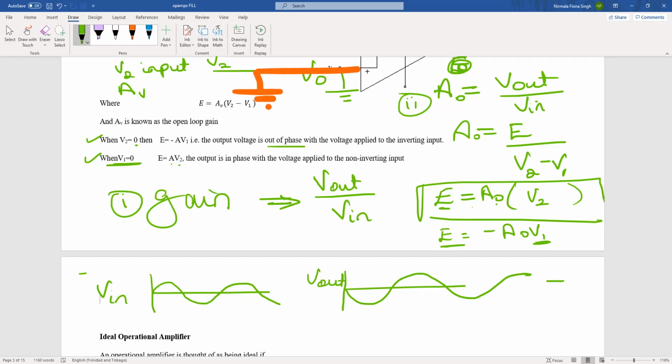I'm sorry to say there are a few topics in here that jump ahead, and there's no way to reconcile it until you know everything. So just to revise what we've just done. One, what is gain? Gain is simply the ratio of output to input. We have three different types of gains. We have regular gain, which is the pure gain, looking at input to output. We have our open loop gain. This is when our signal is not looping back and connecting to each other. And then we have closed loop gain, which we will see in a while. This is where the circuit basically feeds back into itself, or is linked back in a circle.